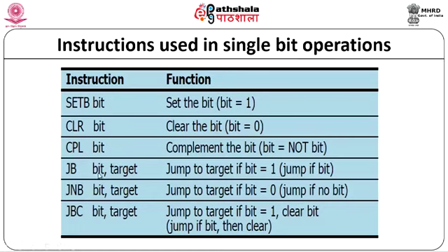So, clear, or reset, is done through this CLR command opcode. CPL is nothing but complement. So, if I give CPL P3.1, what it does is change that particular bit from 1 to 0 or 0 to 1.